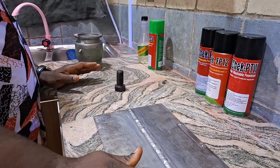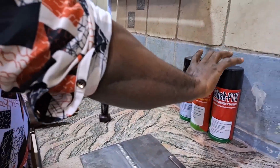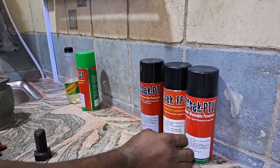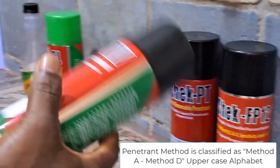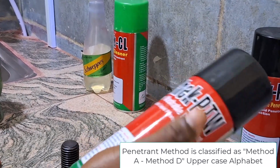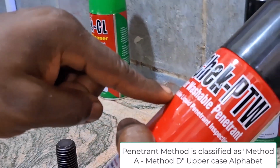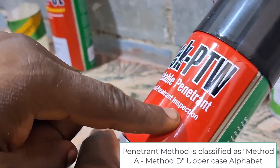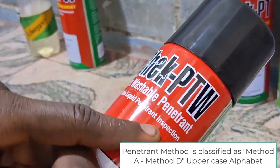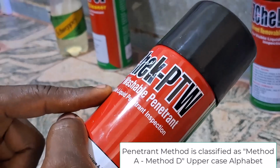After your cleaning, you now look at applying your penetrants. For the purpose of this video, we have three of them here. We have your water-washable penetrant, which is your type A. Now, if you look at it, it's stated clearly that it is for visible liquid penetrant inspection, which means this is 2A.